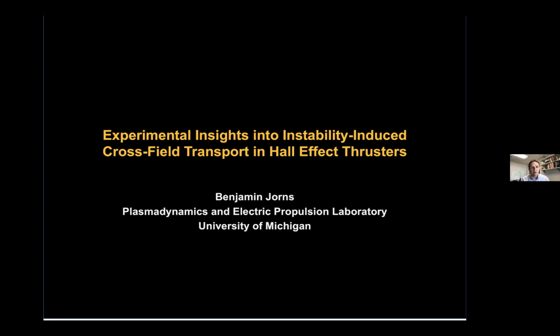It turns out that despite the fact that this device is, at this point, the most widely flown type of thruster in space, there are pieces of how it operates, its underlying physics, that remain poorly understood, most notably related to questions about the internal electron dynamics. In the past 10 or 20 years, there have been quite a few advances that have shed new light onto what causes the electron dynamics to change in the way they do.